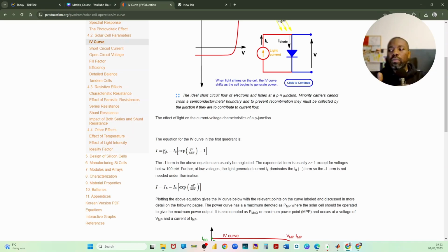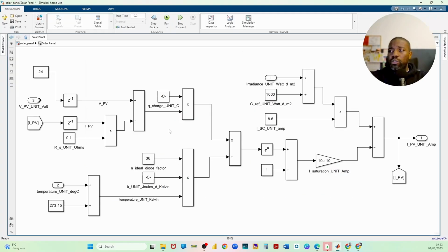And of course, we know that as soon as you have current flowing, there is a voltage drop due to resistance. And then the current that you get at the end is lower than the ideal current without voltage. But for you to get to that equation, the model needs to incorporate all those values, right? So when we're talking about getting to the current coming out of PV, PV stands for photovoltaic, which essentially is the technical term for solar cell.